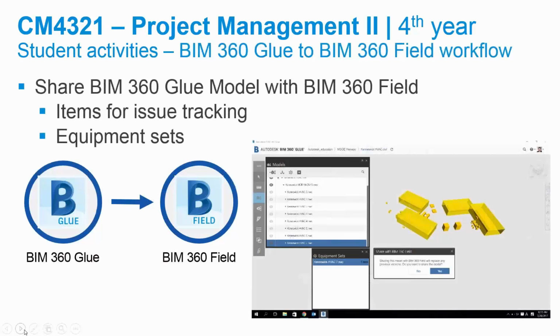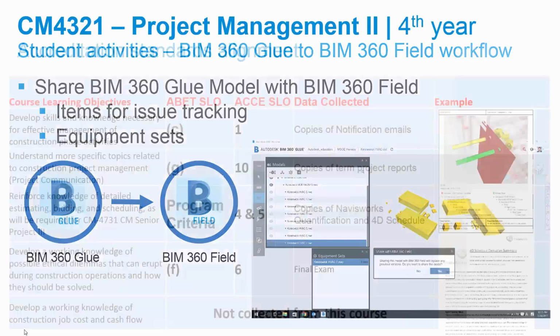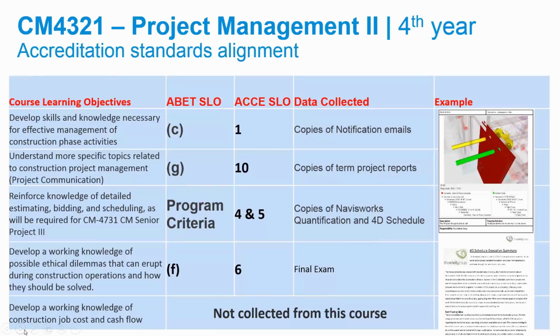Also, the students performed data integration to share a model coordinated in Glue with the BIM 360 Field project. The process is simple as well. After selecting items for issue tracking or equipment sets in Glue, you can simply click the Share with Field button. Once the model is shared, BIM 360 Field users can map the shared model in Field.